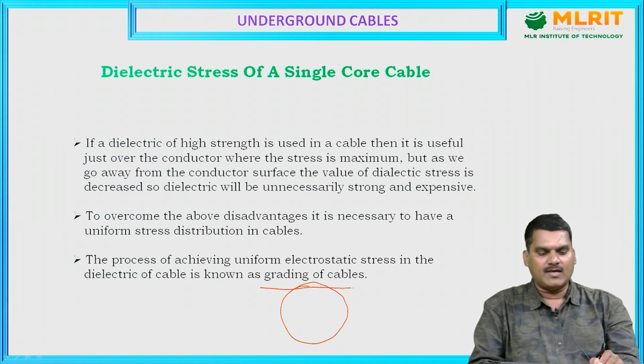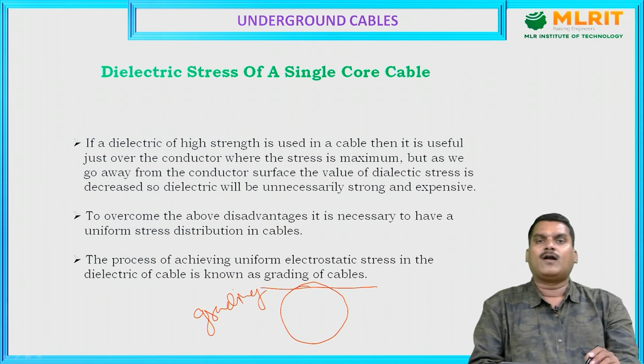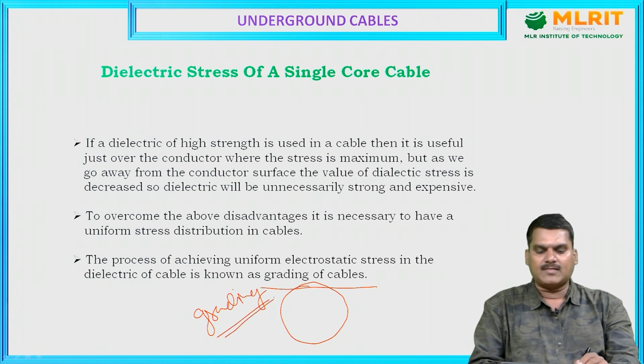That is, making the electrostatic stress uniform within the underground cable is called grading of the cables. By grading, we can make the dielectric stress equal.